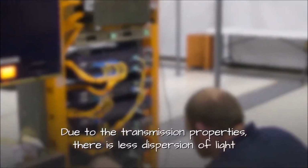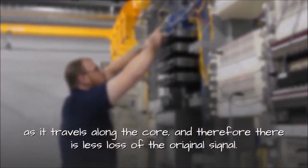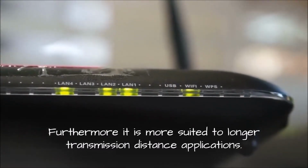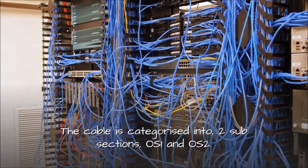Due to the transmission properties, there is less dispersion of light as it travels along the core, and therefore there is less loss of the original signal. Thus single-mode fiber is more suited to higher bandwidth requirements. Furthermore, it is more suited to longer transmission distance applications. The cable is categorized into two subsections, OS1 and OS2.